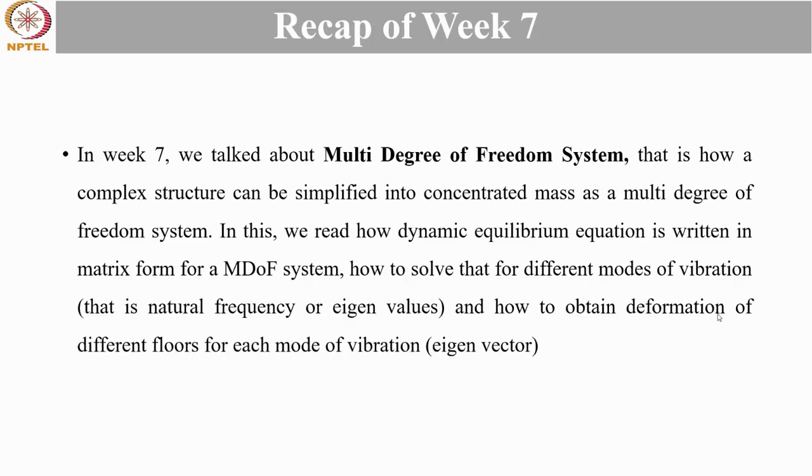Okay, so let's start. During week 7 of the course Structural Dynamics, we talked about the multi-degree of freedom system. That is, how a complex structure can be simplified into concentrated masses as a multi-degree of freedom system. Here we saw how the dynamic equilibrium equation is written for a multi-degree of freedom system, and how natural frequency and deformation profiles are obtained using eigenvalue and eigenvector solution of a determinant equation.